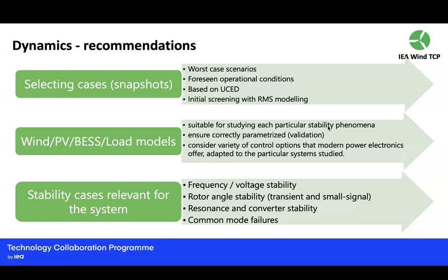On the grand scheme of things, you can take inertia as a simple one. If you're seeing that you have to keep a certain amount of resources online, I will not say synchronous generators, to provide very fast replacement of megawatts that are lost during a loss of generation or a disturbance on the grid, then you need to factor it back into the type of resources being built.